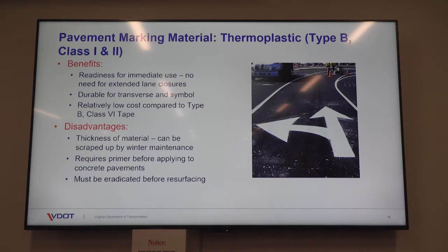When eradication occurs before the milling and paving, temporary paint markings may be necessary. So again, you're going to have to account for those costs for your full life cycle costs, something that we again need to be aware of. It's not just the initial application.